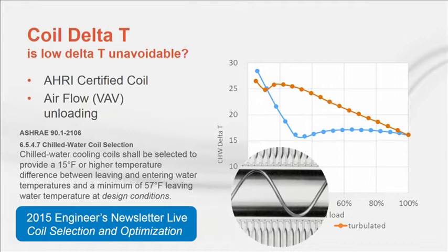This technology is often rejected because of its higher full load waterside pressure drop. But with this type of heat transfer performance, the pump energy penalty quickly goes away at part load. This can provide more efficient annualized operation. Let's set this aside for now, but we highly recommend the consideration of internally enhanced tubes in variable flow chilled water